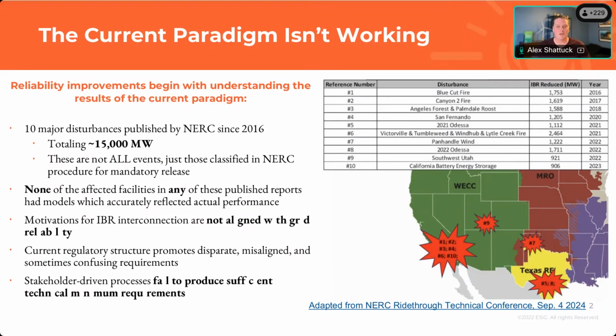What you miss there, and what is a little insidious in a way, is for wind, specifically wind. At the simplest, both Type 3 and Type 4 wind, which are more modern wind, just like BESS and just like solar PV, interact with the power system with power electronics. Those power electronics are susceptible to a number of tripping procedures or events: voltage, frequency, DC voltage, controller interactions, different thresholds, capabilities, and things like that, where even just a simple parameter change or a mistake or a failure to update can lead to the entire plant tripping or individual unit tripping.